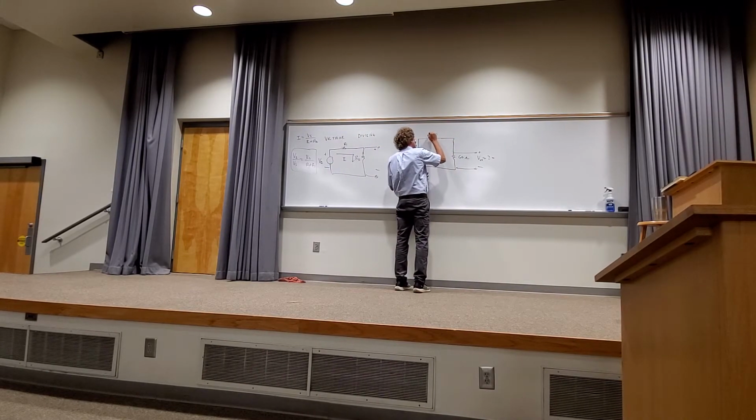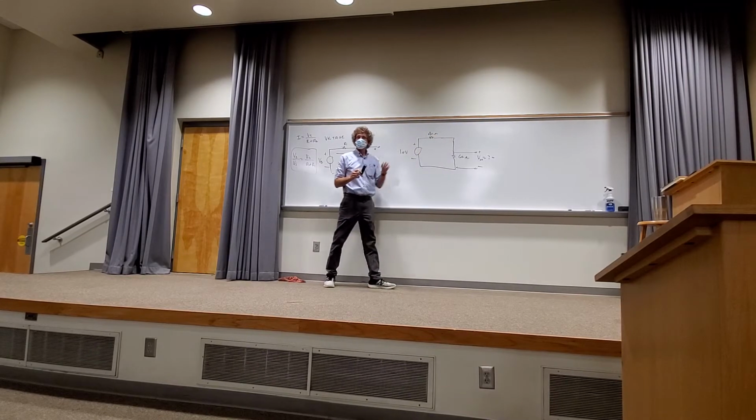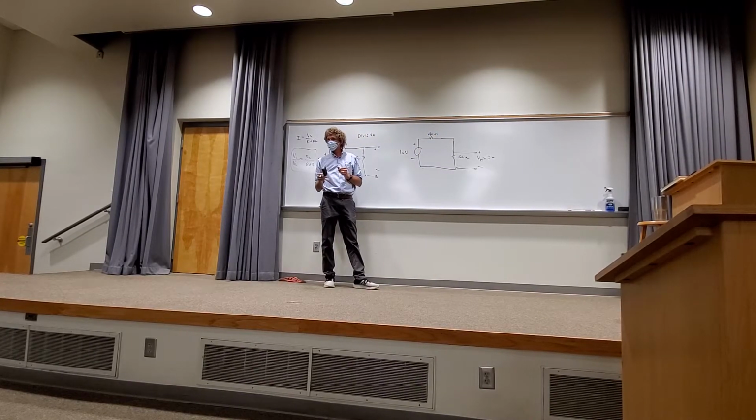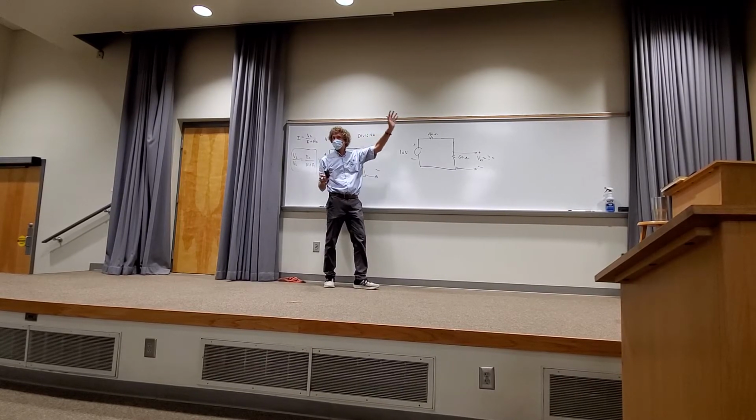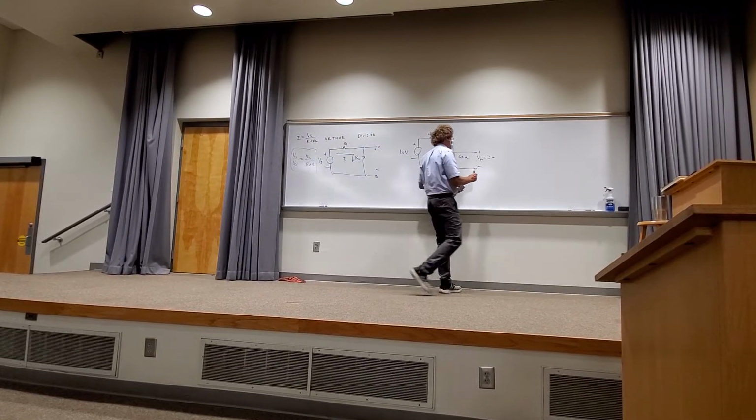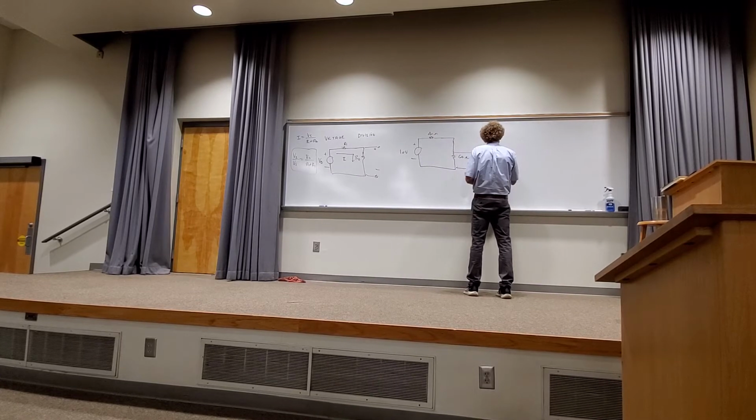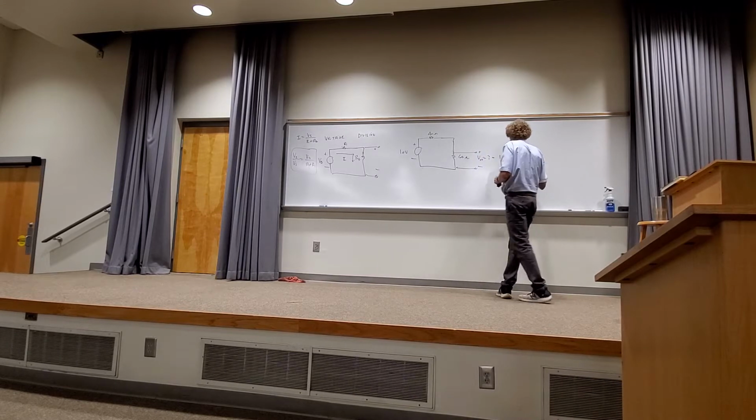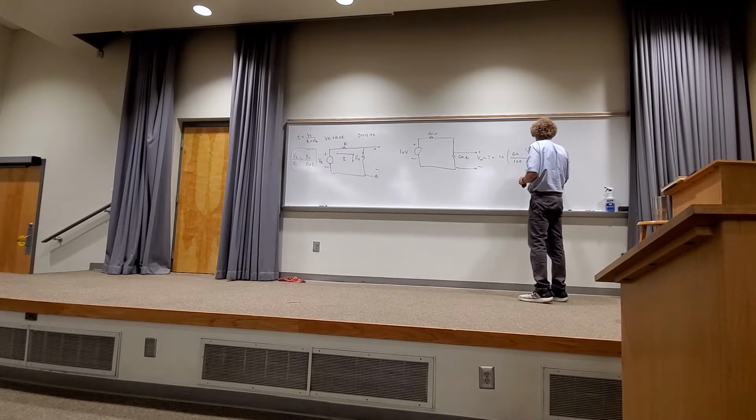Make this 40. Now, do we agree we have two resistors in series with one voltage source? You agree with me, class? How many do? All right. So what do we do? We simply say that voltage is the source voltage, 10, multiplied by the resistance you want the voltage across, 60, over the sum of the two resistances, which is 100, or it's 6 volts.